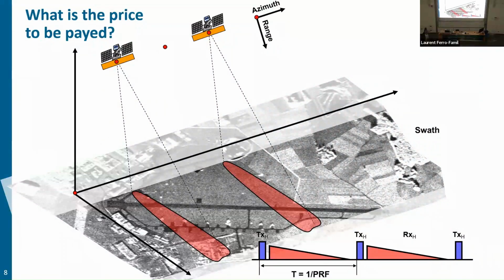The satellite is transmitting the signal here now, let me say in H, a single pole transmitting. And then until it transmits the next pulse with a chirp, what is happening? It is transmitting, and in principle it is receiving the signal back, which is the red part. So there is a reception back to the sensor, depending on the time that you have until you send the next one. If the next one is transmitted, then there is a switch and the reception part is closed. So you have only a limited time in order to receive this.